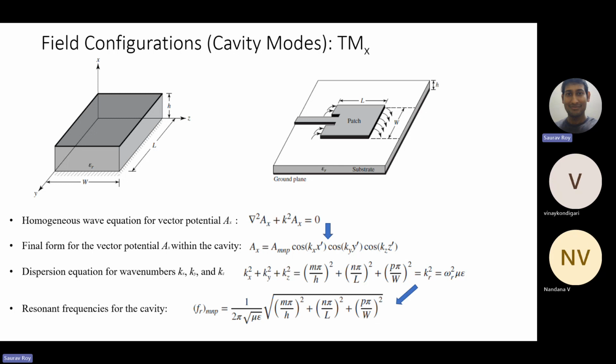And this kx, ky generally gives you the relation with wavelength. So how many wavelengths there will be, that is what it talks about. If you remember, in the rectangular waveguide we used to say how many half wavelength variations we have. If you have a cross b, the aperture of a rectangular waveguide, we used to say TE10. TE10 means 1 is one half wavelength variation in the x direction, and 0 means there is no half wavelength variation in the other dimension.